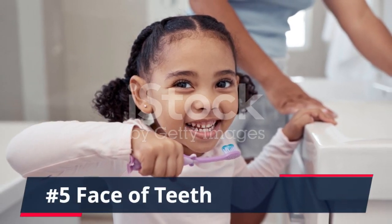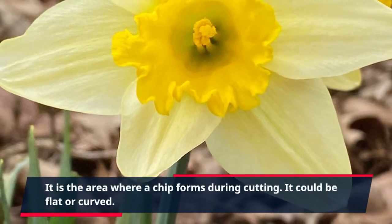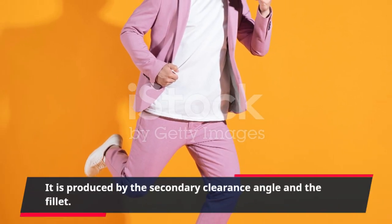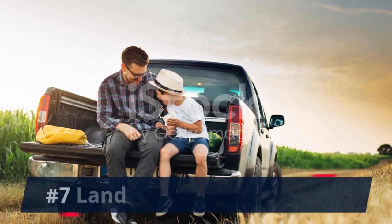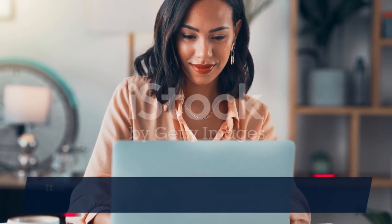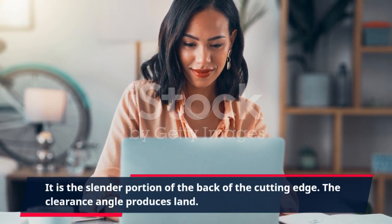Number 5. Face of teeth. It is the area where a chip forms during cutting. It could be flat or curved. Number 6. Back of tooth. It is produced by the secondary clearance angle and the fillet. It is the slender portion of the back of the cutting edge. The clearance angle produces land.